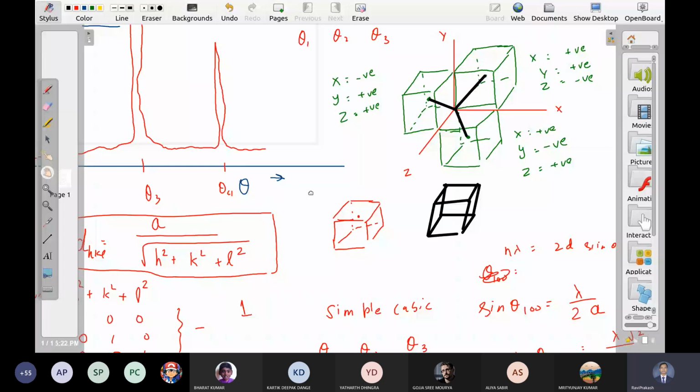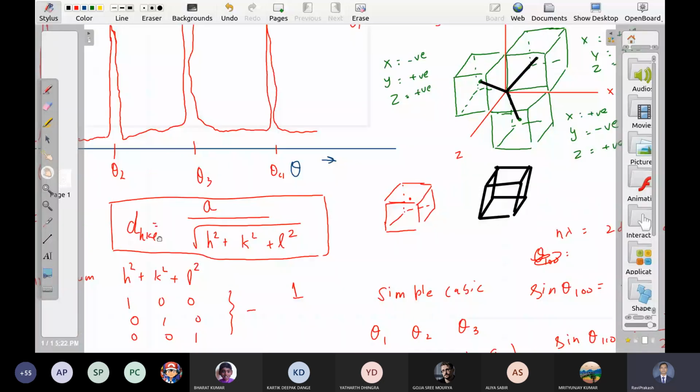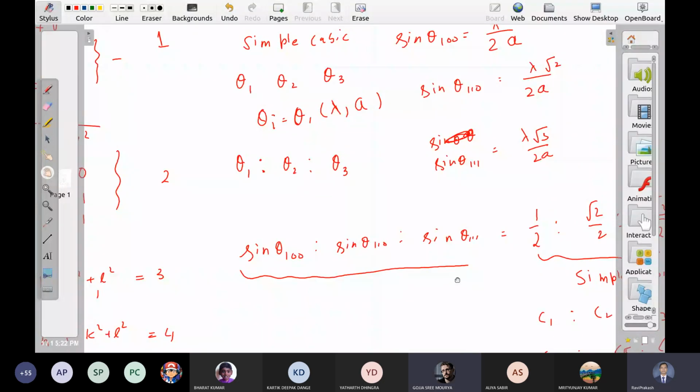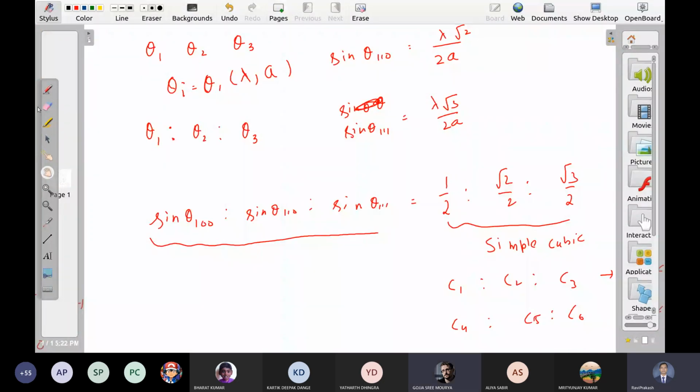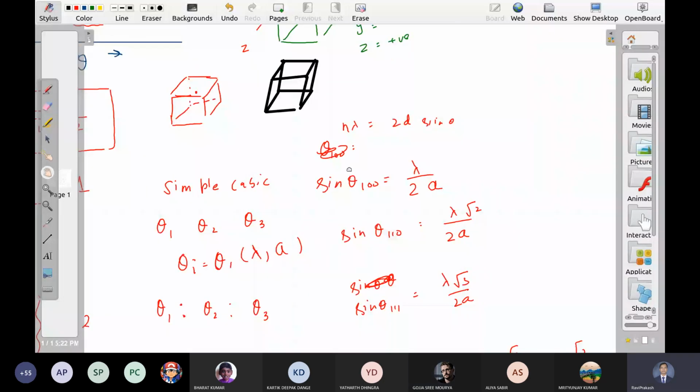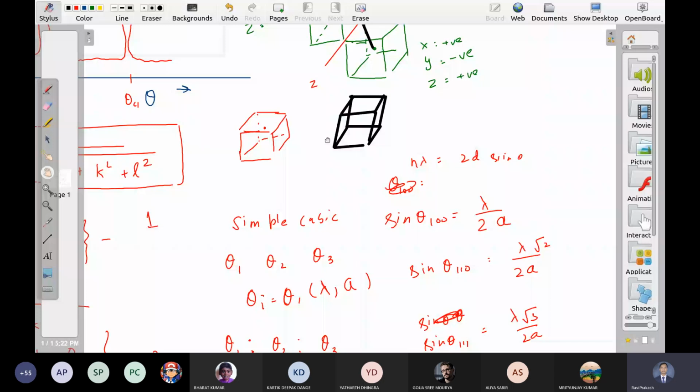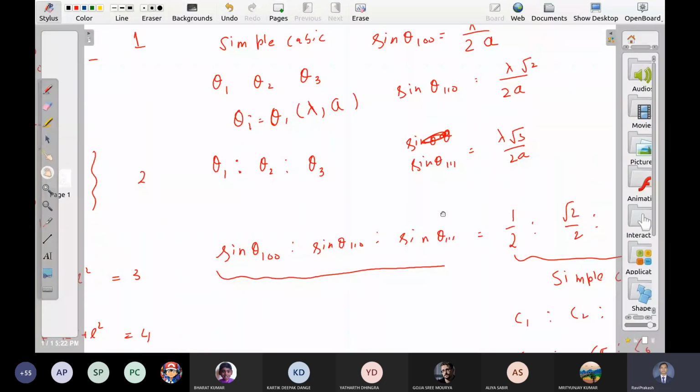When is this formula working? When all these three vectors are perpendicular to each other. So this formula will also get modified, and accordingly this whole calculation will get modified, and we will get some other set. Yes, it's like a parallelepiped, sir. So the interplanar spacing will also change accordingly. Use this new interplanar spacing, use that new formula, and again calculate all these things. This is a difficult calculation, but it is a one-time calculation.